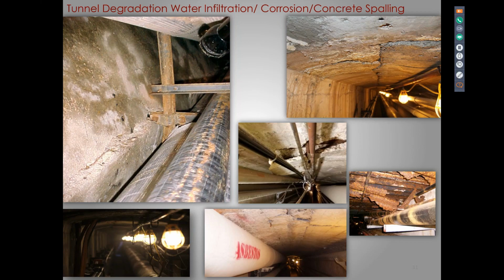So it's critical you understand where those challenges are and then also monitor them on a routine basis, because things can change quickly. Yeah, and I guess I just go back to that. We saw that pretty-looking BIM picture of how everything is. Reality is a little different than that. So part of our condition assessment in the tunnels is documenting these kinds of situations. Some of them look really scary, but you have to look carefully at them and make sure that this is really a high priority. The case that Chris talked about, there was a visible crack right over top of this steam line, and sure enough, it caved in a couple of weeks later. So that was a high priority.